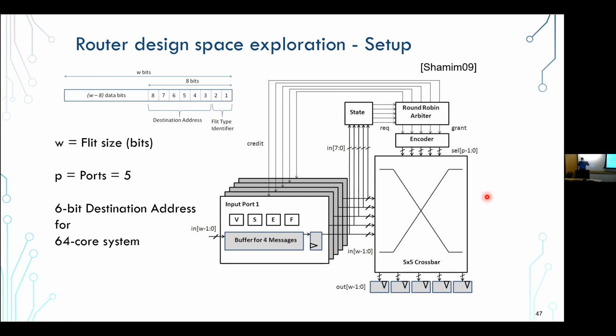encoder or decoder to tell me, let's say in this round, port number 1 has the priority, right? And everyone else is lower priority in descending order. And I'm looking at which port wanted to go to that output port. Whoever is the first on that priority list goes. Next time around, I decrement the priority by 1, so everyone shifts.